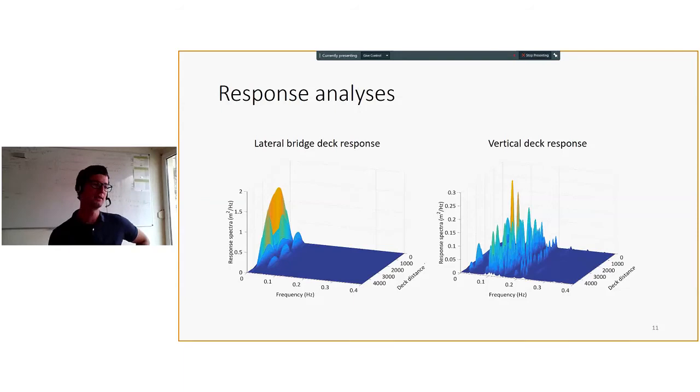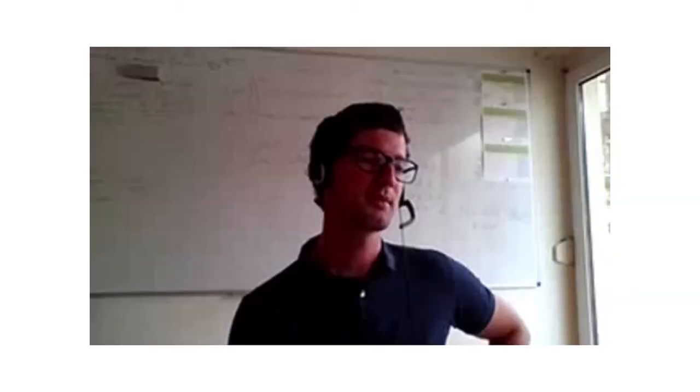And what you can see here in the lateral direction is a huge response for the first mode. We measured those responses to be about 12 meters for some 30 to 40 meters per second wind. So these are quite large displacements, and as well we have a lot of...